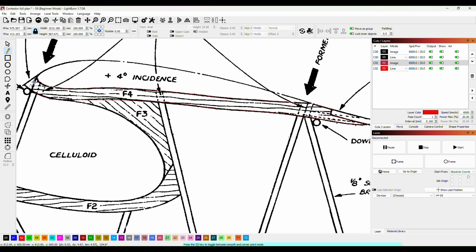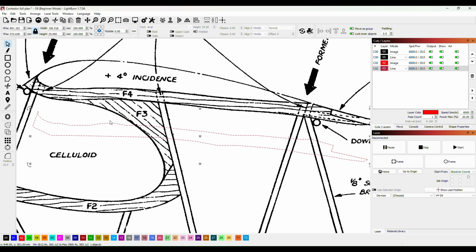and then I'm going to come round and reach this point here. Now when I come up a little further, when I come up to here, if I snap, click on the near the start point, it will snap together, and now I've got a single line where I've created that shape there. So I can actually move that out. You can see there's a couple of places here where I've wobbled a little bit, but what I'll do is I'll smooth all those out using the node tool in a minute, and we'll be fine.